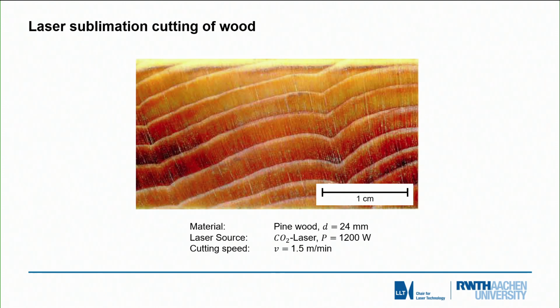This is an example of a cut in wood. The thickness is about 2.5 centimeters, and you see a kilowatt CO2 laser is sufficient to cut that with about 1.5 meters per minute speed.